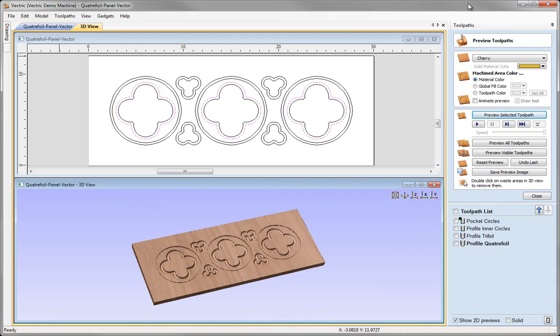So at this stage I have another toolpath I'd like to calculate that's also going to use the 1/2 inch ball nose tool. And typically it makes sense to keep groups of toolpaths together that do use the same tool, because you do have the option within the software to save those as a single file if that made sense for the way you wanted to cut the part. So in this case we could output all of the toolpaths that use this 1/2 inch ball nose as one file, and then the machine will just consecutively run those in whatever order we save them.